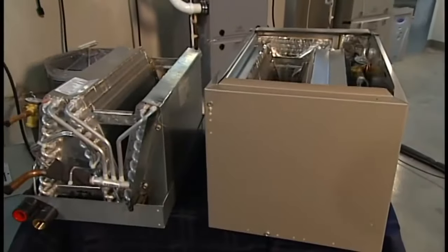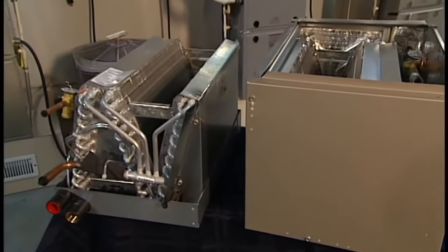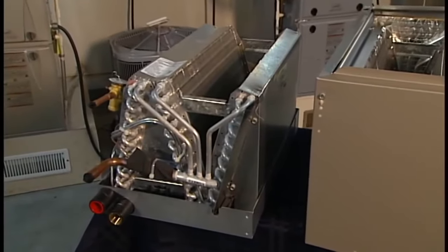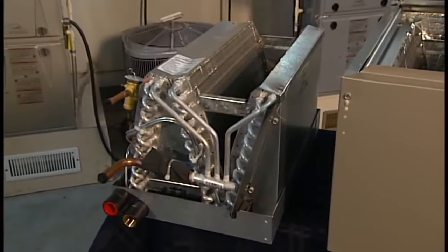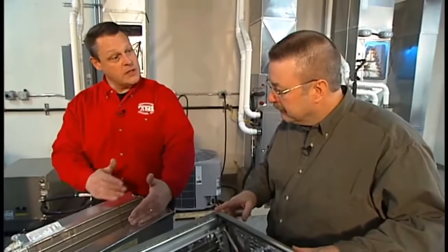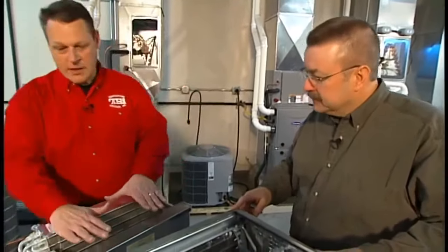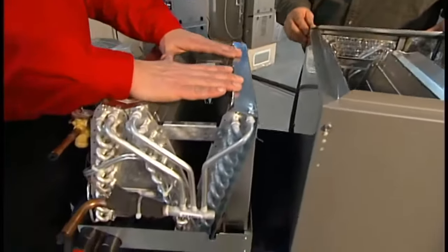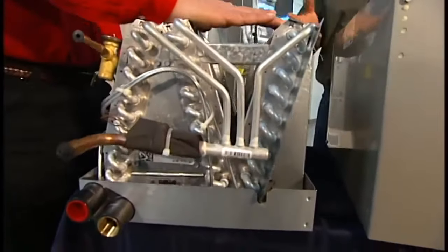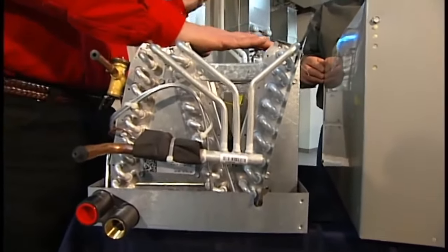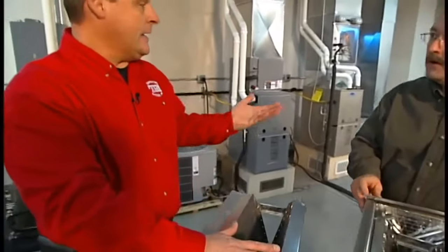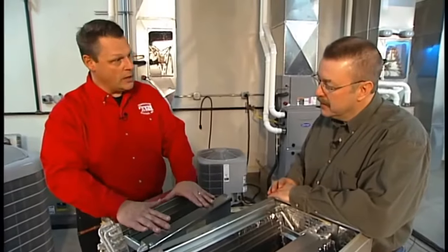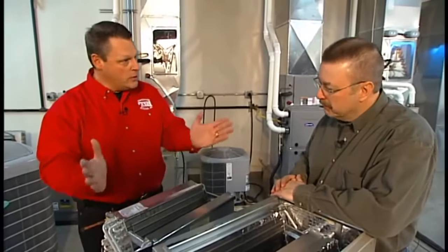They look a little different in shape, but are these also the coil? Yeah, these are still an evaporator coil like we looked at, but with today's efficiencies, we have to come up with a little different configuration to give us more heat transfer surface to get us a higher efficiency. This is an N coil. It happens to not have a casing on it because usually this is used for our retrofit market. In an existing furnace, we may be coming into somebody else's brand. It doesn't necessarily fit as a cased model, so what we would do is come in with an uncased, customize the plenum around it, and you're good to go.